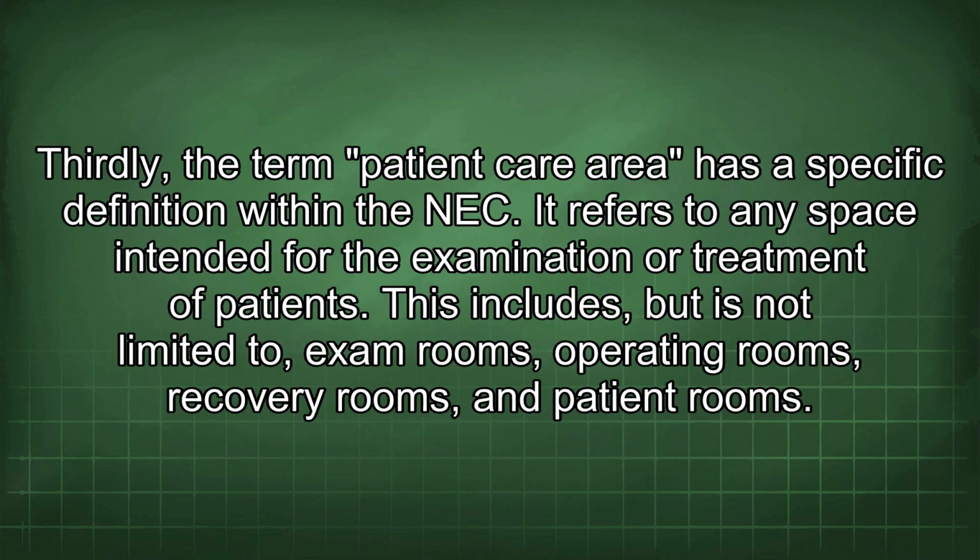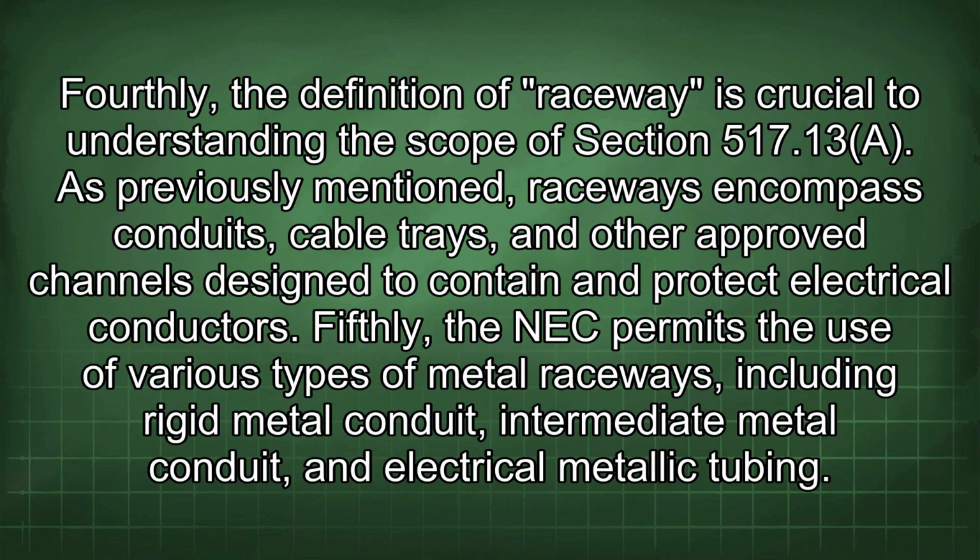Thirdly, the term patient care area has a specific definition within the NEC. It refers to any space intended for the examination or treatment of patients. This includes, but is not limited to, exam rooms, operating rooms, recovery rooms, and patient rooms. Fourthly, the definition of raceway is crucial to understanding the scope of Section 517.13(A).